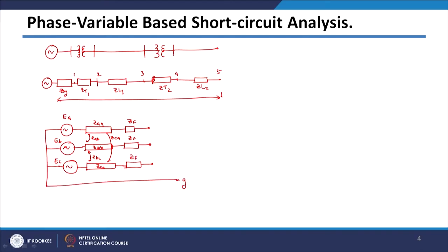and this ground I have taken here, I am calling it the G point, and here I am taking one X point. So, this is your A phase, B phase and C phase, and this X point. This arrangement I have done, that is ABC and XG, so that I can create different types of fault in this network, and I can calculate fault currents easily. So, the fault current in A phase is IFA, the fault current in B phase is IFB, basically this current, and this current is IFC. So, fault currents IFA, IFB and IFC here.